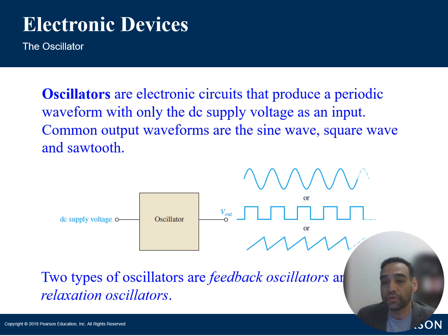So there's a phase shift component. And by that I mean there's an innate phase shifting that occurs. So in many oscillator circuits, we have this shift, and it's introduced in the feedback loop. So the phase shift is crucial for sustaining oscillation. So for instance, in a phase shift oscillator where you have an RC network, or you have some active component that's used to create this 180-degree phase shift, that gets fed back into the feedback loop, and that'll sustain the oscillation.